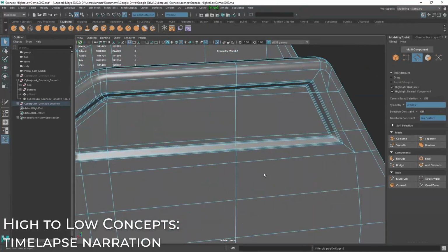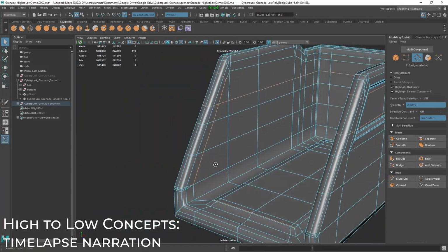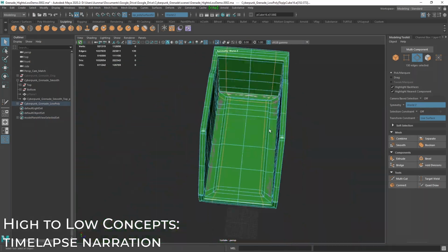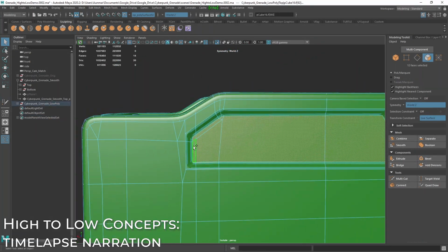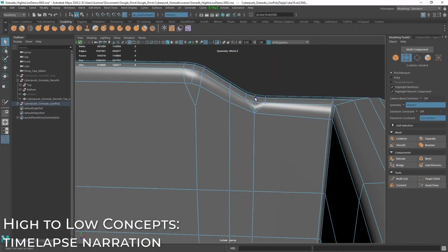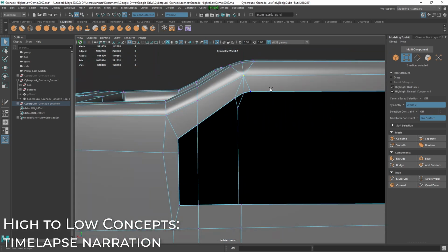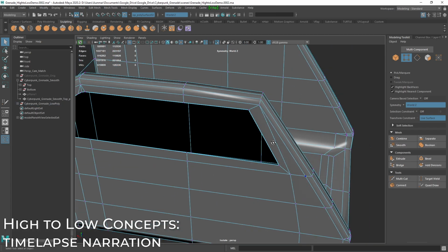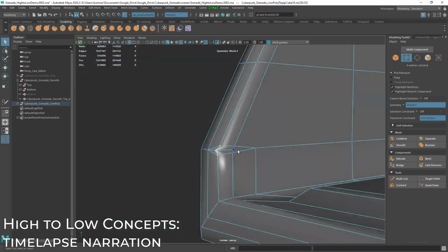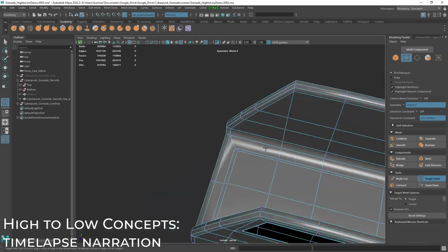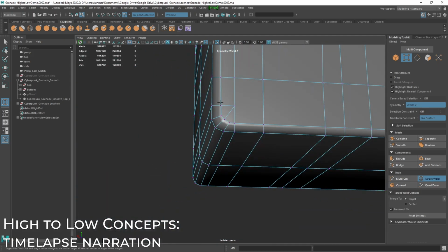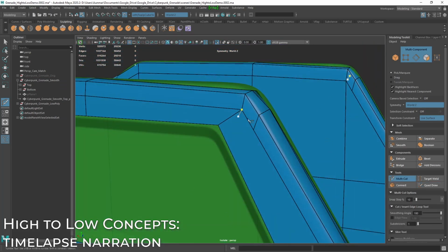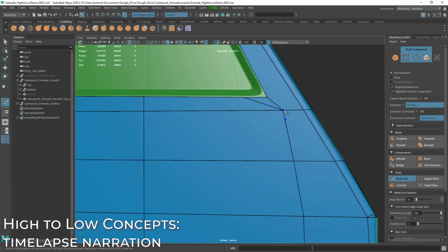and you can see that I'm beginning by just taking and removing all of the holding lines and edges. And I do a little bit of cleanup, and this is where I deleted that inner piece, that inner inset, and then I ended up just using quad draw there. So I'll go ahead and let that go through, and then I kind of keep those corner pieces because it is a pretty wide radius for the corner, so I kept that there.